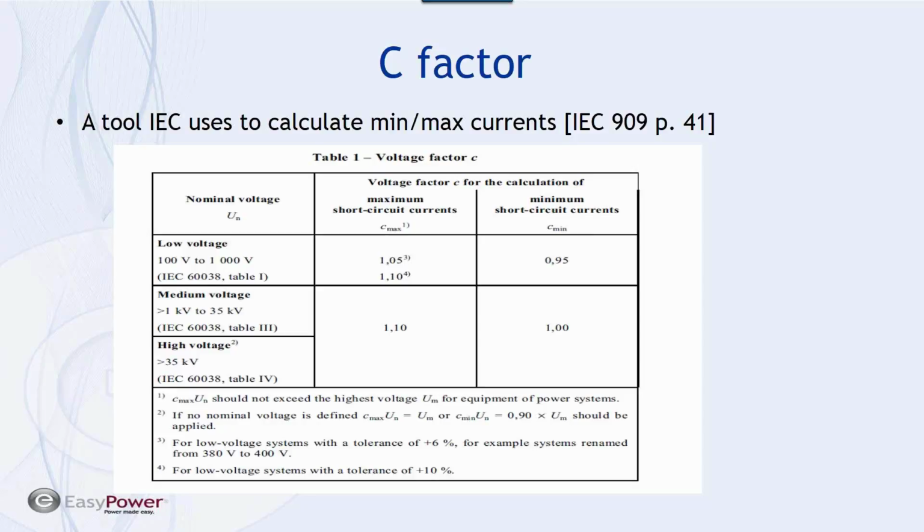Why do we do that? For very obvious reasons. You're looking for rating your equipment, you're looking at your buses, you're looking at the protective devices primarily to find the ratings and see whether or not they can withstand those fault values. That's how you achieve it in IEC, by changing Cmax and Cmin.